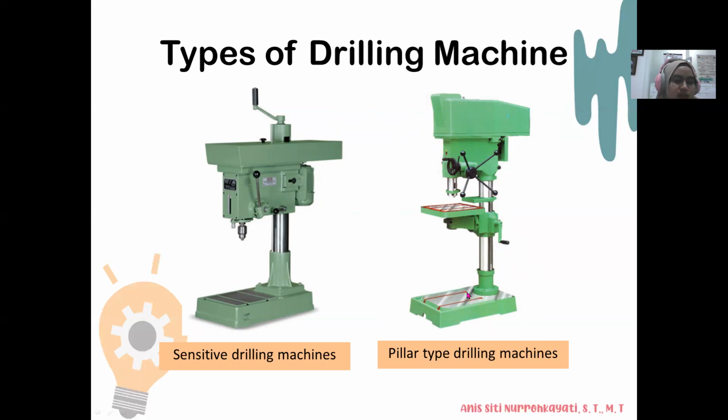The vertical column can be either of rectangular or round section. The latter offers the advantage that the table can be swung out and slightly bigger jobs can be accommodated on the machine base instead of the table. The drilling head can be lowered and the hole drilled in the job.